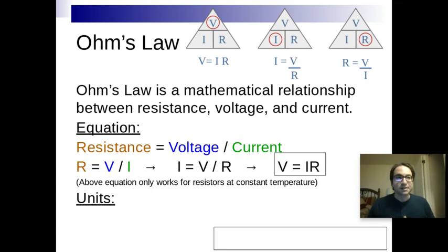And that's what a dimmer switch does. I'm sure many of you have either knobs or sliders on your light switches, and the lights can get brighter or dimmer. Well, that's a variable resistor. You turn the lever up and the lights get brighter. Well, you're actually decreasing the resistance then to allow more current into that light bulb, and therefore it glows brighter with more power.